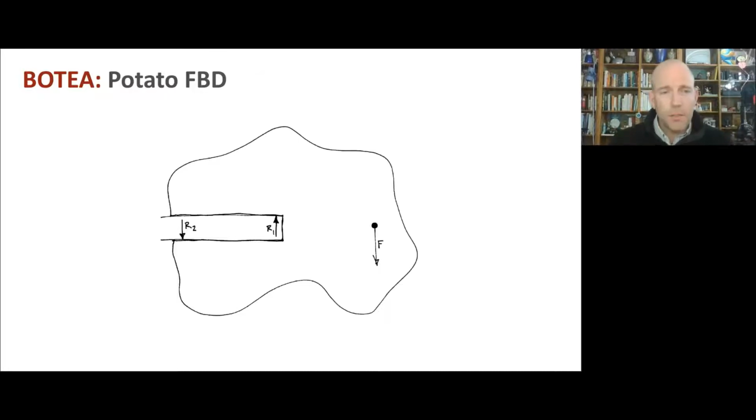Another thing to think about is, do we need friction in order to achieve static equilibrium? And the answer there is also, it's going to turn out to be no, right? We haven't drawn any friction forces here, but we can achieve equilibrium in this case. And then the third thing to think about is, is the assumption of no friction a conservative or optimistic assumption? And in this case, it will turn out to be a conservative assumption.